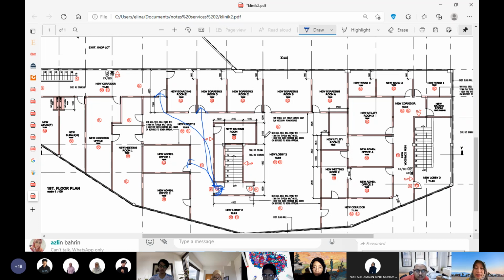Protected means they have to close it up; it cannot be an open staircase. When fire breaks out somewhere here, this brick wall can stay up for 1 or 2 hours, so you can evacuate the building using this fire staircase. But you have to understand the dimension and the distance here. Within 1 hour, how can the people from the new corridor and the new admin escape?